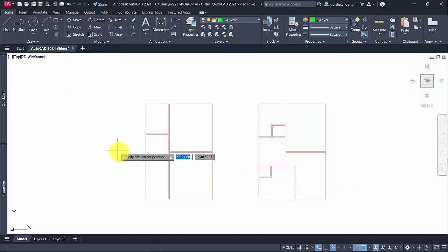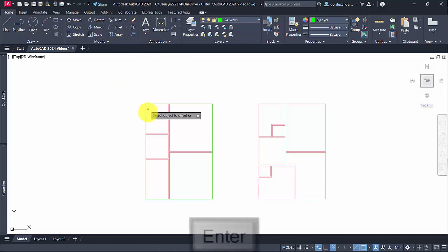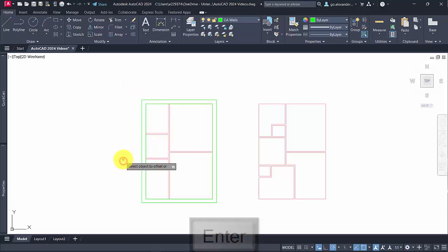And let's just double click on that to make it current. So what we can do is draw a rectangle over the outline of the layouts for the ground floor here. This is a semi-detached house, so we will need to fix that in a moment, but we can offset a distance by 350 millimeters. And that is 100 millimeter inner leaf, 150 millimeters cavity, and 100 millimeters outer leaf.